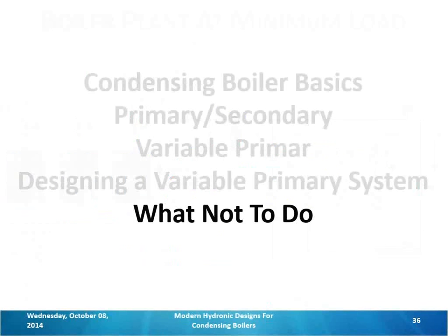But with no isolation valves, the way the math works out, this boiler has to supply 220-degree water in order to meet that 160 downstream. And I mentioned earlier, condensing boilers, they lock out around 200 degrees typically. So somebody's going to be going down to that room and hitting the little red button.